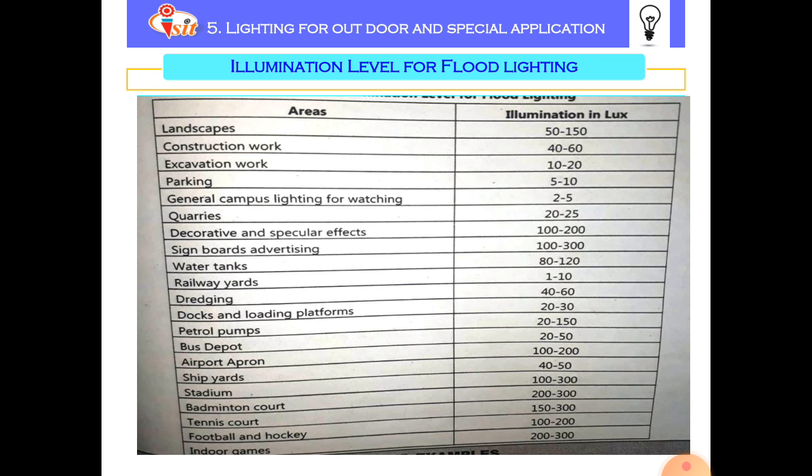The specific requirements of flood lightings are: the brightness of floodlight should be sufficient to stand out in contrast with surroundings. The illumination should be sufficiently uniform all over the working plane. The lighting should not cause reflected glare at the normal viewing position, so that the people or observers can see the images or the premises without any obstacles or any harmful pain or strain on the eye. The lighting equipment should not prove to be an obstacle.